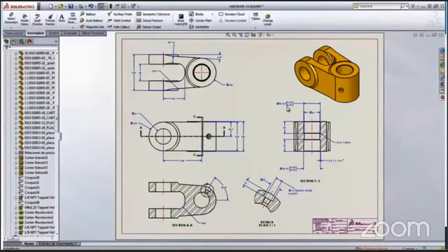So in this task, what we have done is import the knuckle body, which is actually a subcomponent of the assembly. We performed a static simulation analysis on the knuckle, and after seeing the results, we modified our part, which did not impact our assembly or drawing, as they are automatically updated.